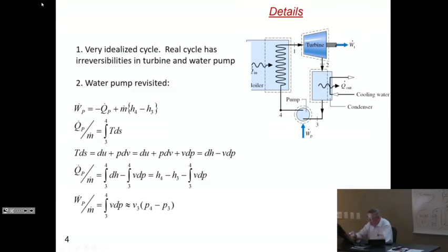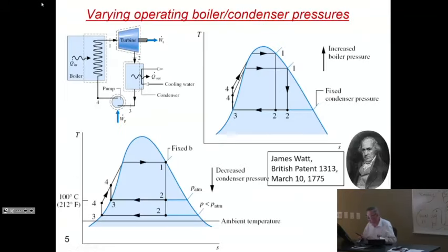So this is a much more accurate way of calculating the pump work than the classic PdV, simply because in the classic PdV, the dV is small, the P is very large, so you have no accuracy. Here, you have accuracy. So that's one subtlety. This is an equation you actually probably need to remember because it's hard to derive, and you'll find it in your book.